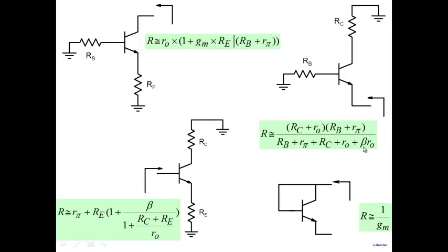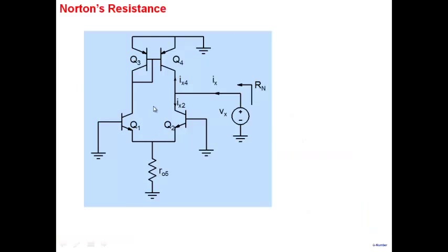And R pi by beta is what? 1 by Gm. And 1 by Gm is like a very, very small resistor here. Okay, extremely small resistor as compared to this R05. So what happens is, the moment the current arrives here, it sees a large resistance here and sees a small resistance here. So it bypasses R05. It forgets about R05, continues here. Same current flows here.